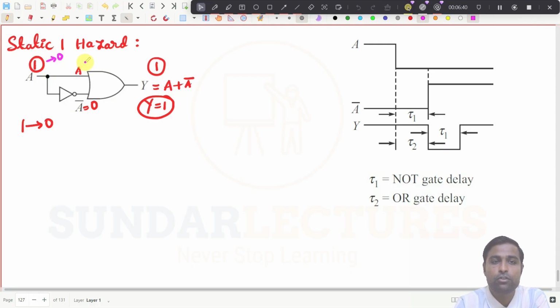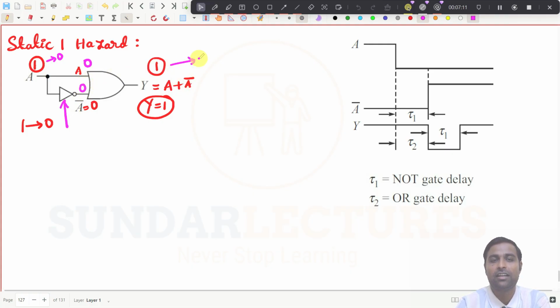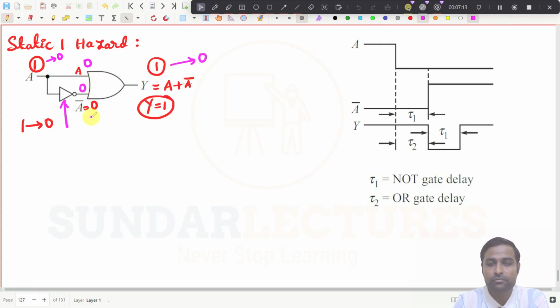This is going to become 0. So straight away this one is 0. But what happens here? This particular NOT gate has propagation delay. So this 0 will not become 1 instantly, and it takes its own time to make this 0 to 1. So this one will be 0, and if both inputs to the OR gate are 0, then obviously this output is 0 now.